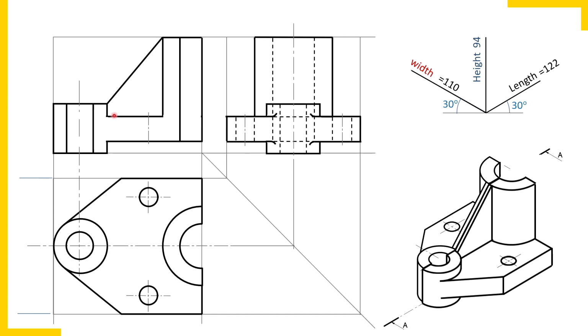Now draw end projectors. This is the length of the trapezoidal plate. And draw the strip between the semi-cylinder and the cylinder. Thickness is 10 millimeter, to be measured as 5 millimeters above the center line and 5 millimeters below the center line, so that you get a total thickness of 10 millimeter. The top view is symmetrical, so of course you draw this strip symmetrically.